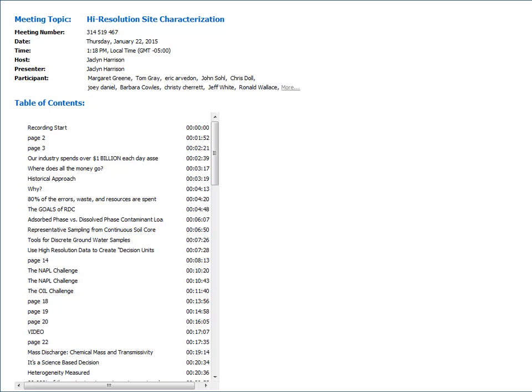To me, that's one of the best uses of the tools. It's really what I call a diagnostic evaluation. If that's the situation, why do we still have the problem? So you have one of two issues. One, we haven't got the source zones identified, or two, we don't have all the transport zones identified, and the down gradient wells are not monitoring the right depth intervals. So I think it's an excellent use of the tools, and it's typical of a lot of the projects that we get into. How did it get in my neighborhood, so to speak?